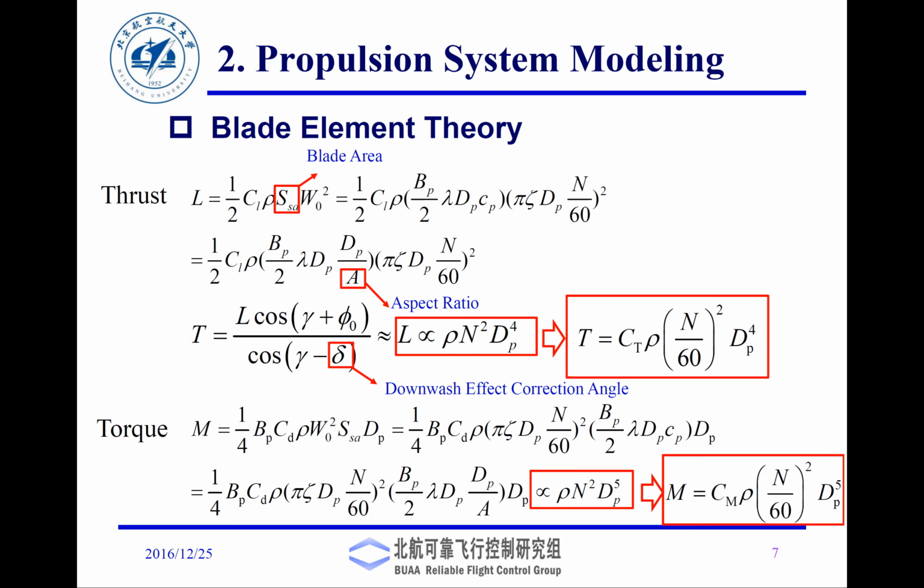Now torque. Once you look at the equation for torque, please understand the thrust equation has its roots in a coefficient of lift, CL. Can you see CL is popping in there? The torque is dependent on CD. So basically, you would have the same thing: CD multiplied by 1/2 rho V squared multiplied by the projected area. And please note, torque means you have the force multiplied by the radius. So that's why that gets multiplied with one more D.